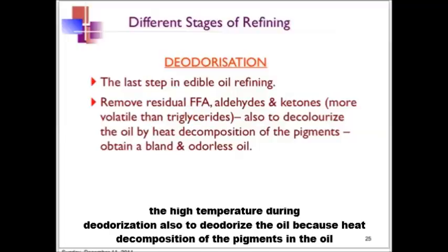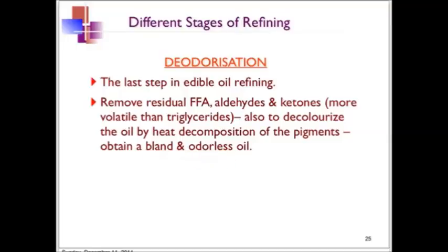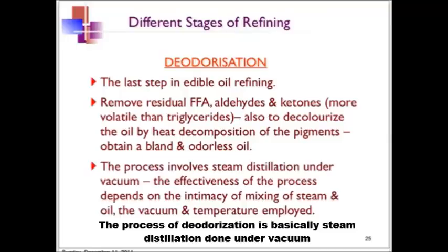The high temperature during deodorization also would decolorize the oil because it will decompose the pigments in the oil. So the final deodorized oil will be bland and odorless. The process of deodorization is basically a steam distillation done under vacuum.